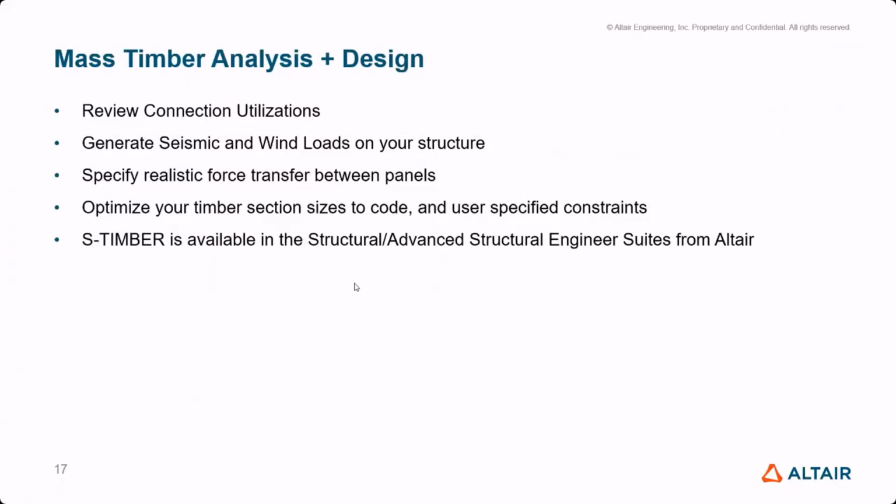So that brings me to the end of the presentation here. As you saw from S-TIMBER, it's available to do mass timber analysis and design, but it can actually just do general structural analysis and even steel design as well. Some of the newer technologies that we've added to this allow you to look at the utilization of your connections and also calculate the forces going through your connections. It can also allow you to generate a variety of different types of loads, whether it be seismic loads, wind loads, or load combinations, or load cases.